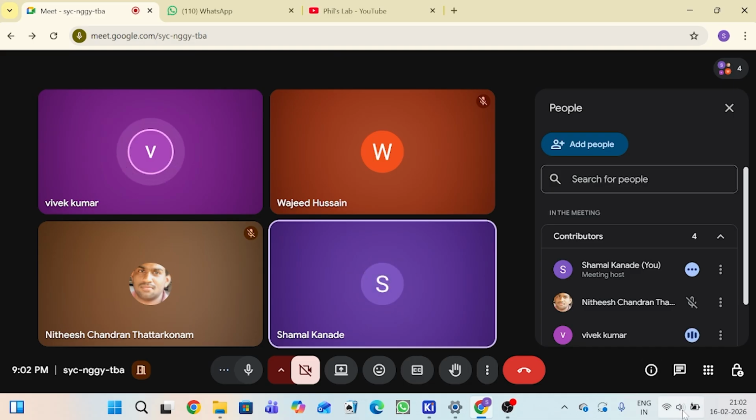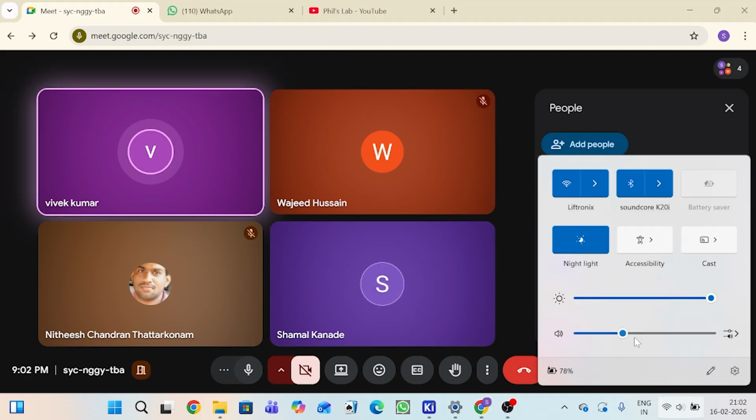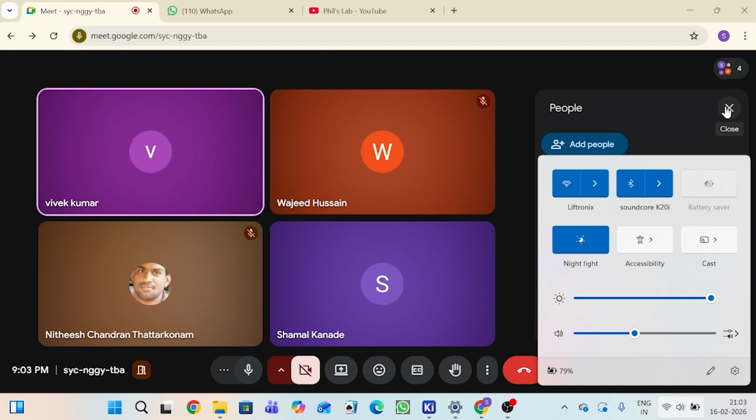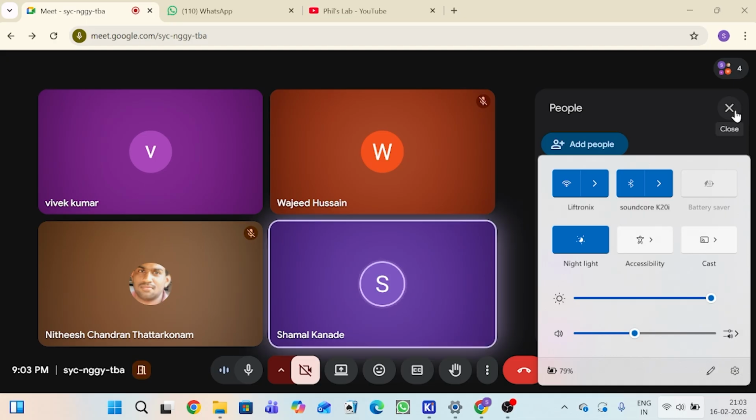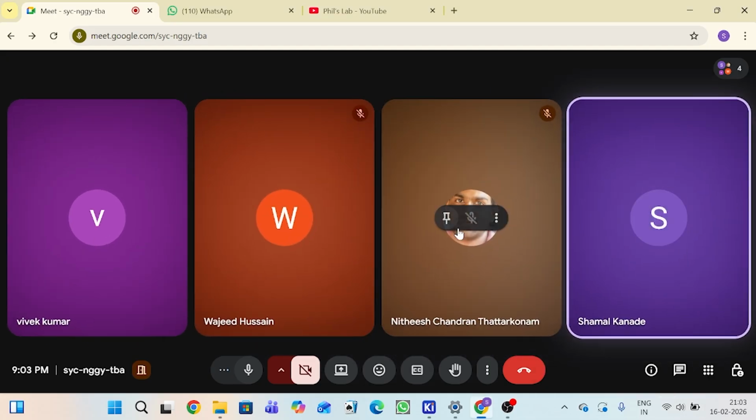Yes, ma'am. I have a doubt about how to add a footprint, because I downloaded that version you marked in a screenshot, but for me the footprint is not showing. Only symbols are coming. It's not an issue. We can assign the footprint one by one. How can we do that, step by step?